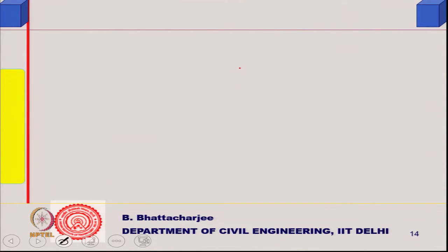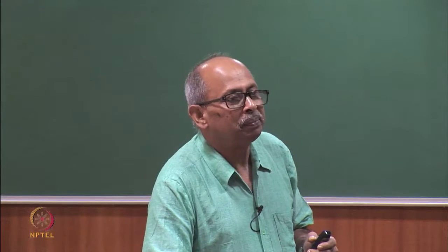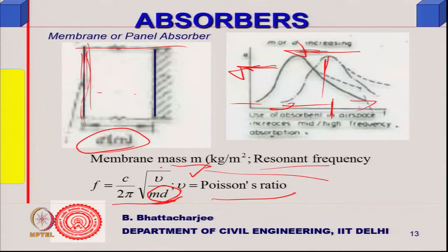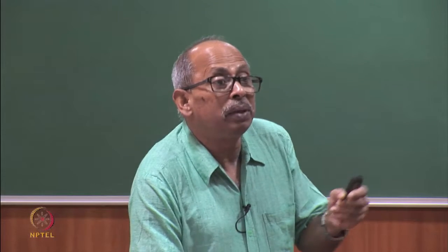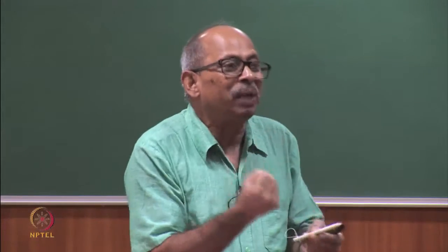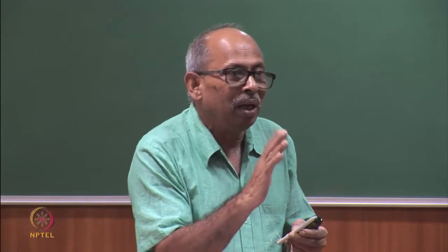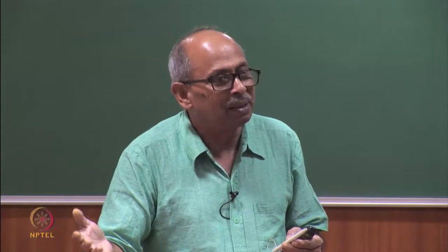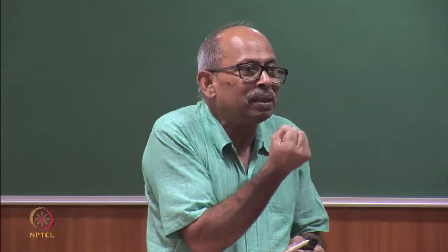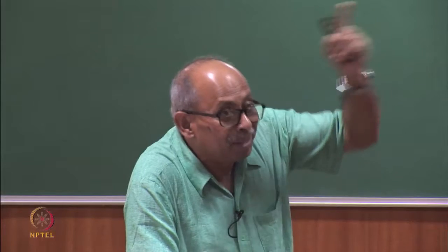So, the absorptivity depends upon the mass per unit area of this membrane. This particular frequency corresponds to the resonant frequency. At the resonant frequency, because of its resonance, it will not allow energy to come back, it will absorb that energy. The membrane itself will resonate, it will vibrate quite a lot and will not pass back that energy to the space. So, in a way the structure itself holds the energy together. So, the hammer kind of thing is occurring there in the membrane itself.